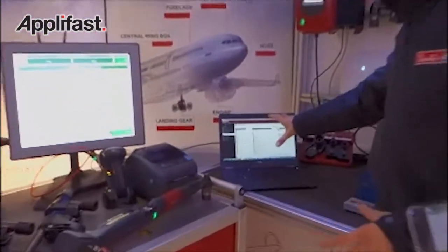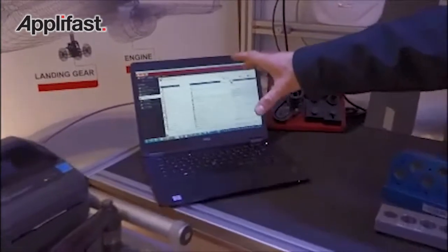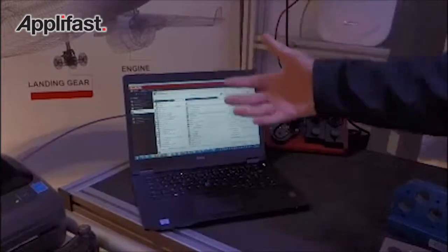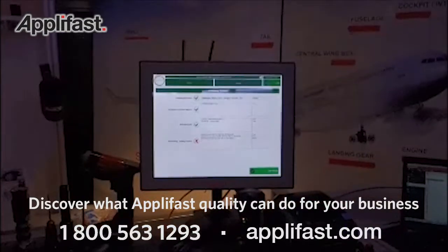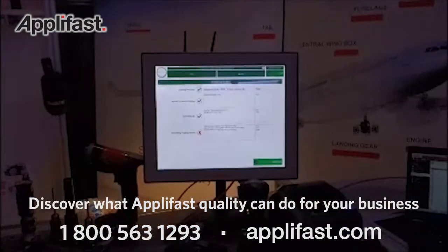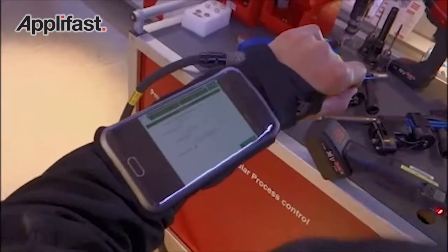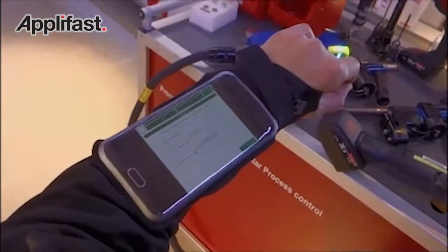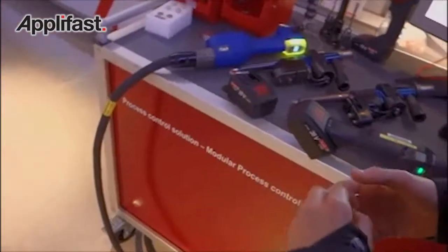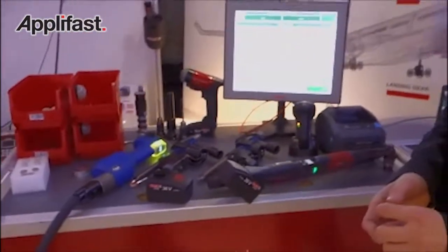What we've got on this laptop is a software called CVI Fusion, where you will create and build the aerospace assembly sequence. Then we move to this part where we have the screen, which is basically the HMI, where the operator can follow the different sequence of the operations. The same operator can follow, if necessary, and pilot the full sequence with a mobile HMI that can be with the operator. So really useful when you go to a large fuselage section. Or we could think as well about some potential projection solutions.